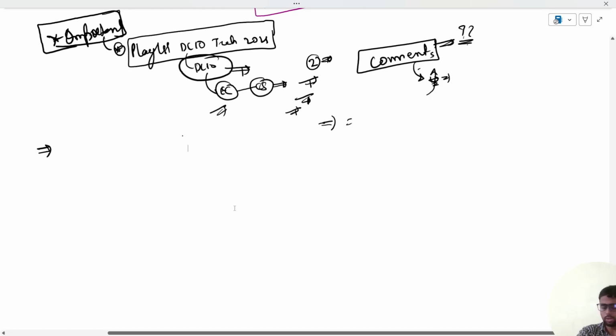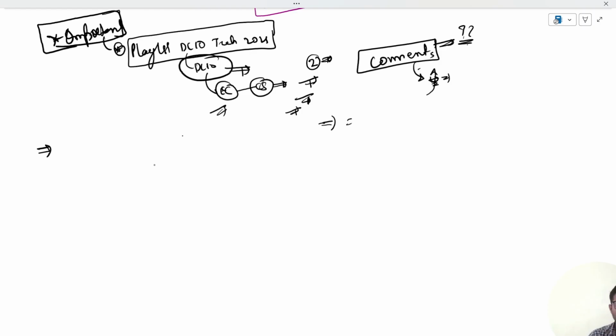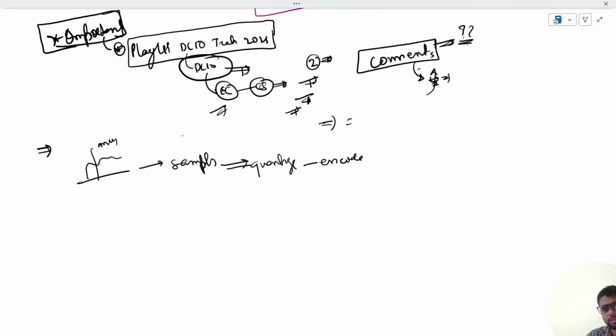So, hello friends. In the last video, we have seen digital communication, especially pulse code modulation. We have seen that the continuous time signal m(t) is converted into samples, and these samples are further quantized and then encoded, and then we are left with bits or a stream of bits.